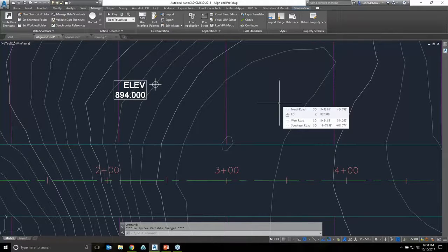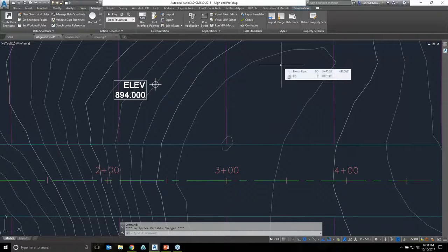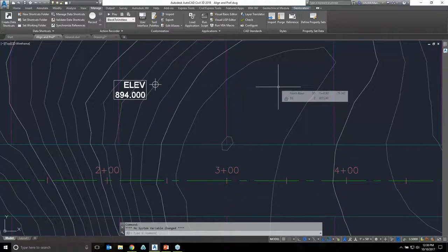I could play around maybe with trying to trick it by naming it the exact same, but again, I don't think you're going to be able to force an override of a style that existed in that drawing by referencing a different style into that drawing. It's going to have to have started out as a reference. It's just going to have to be a reference, unfortunately. So yeah, not necessarily a way to force an override of something that was already in place.